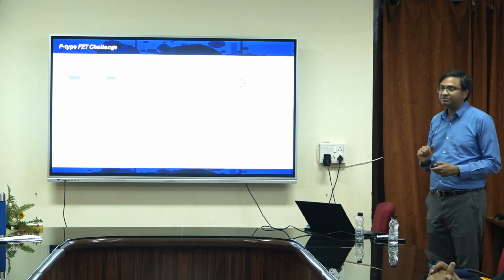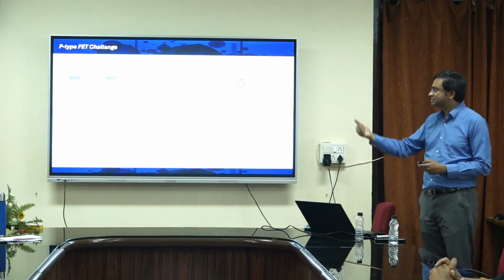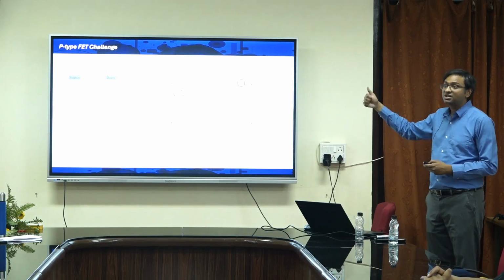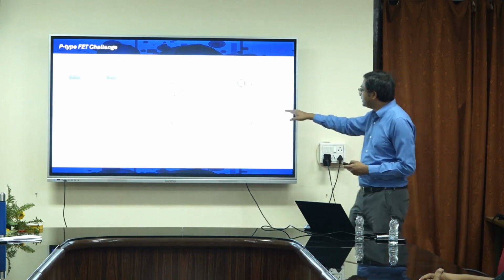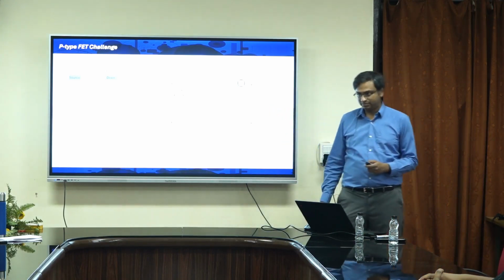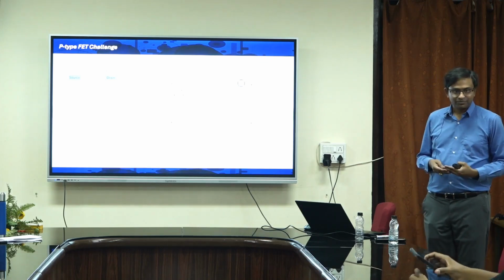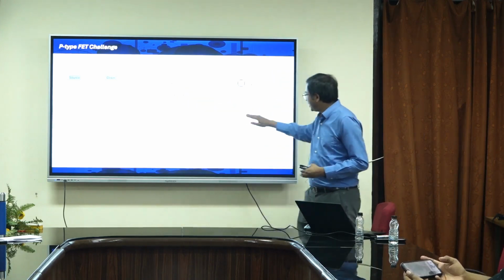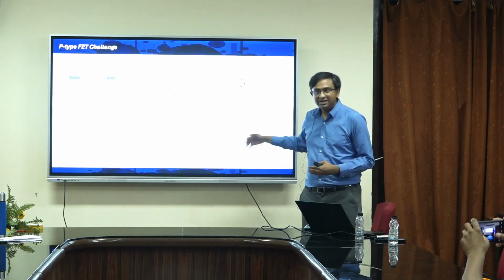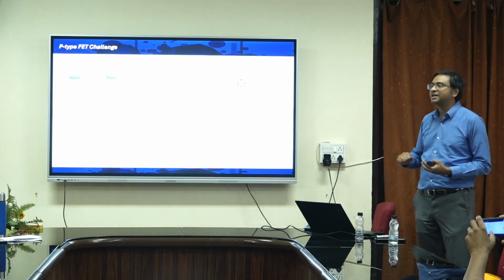But this is not allowable for the materials which show more intrinsic P-type characteristics, like molybdenum selenide or tungsten selenide. The problem with these materials is the Fermi level is pinned mid gap. It was almost like neither here nor there, okay? Here it becomes N-type; if it were on this side, I would have been benefiting, right? But the problem is it is mid gap.